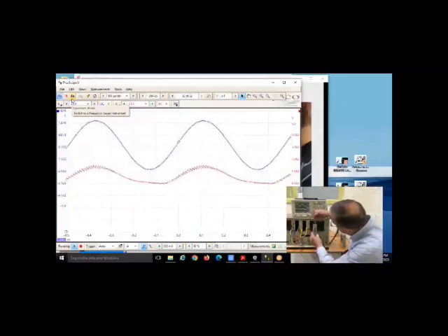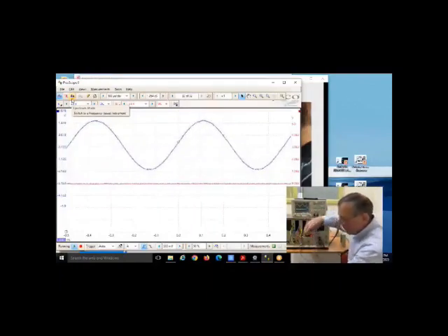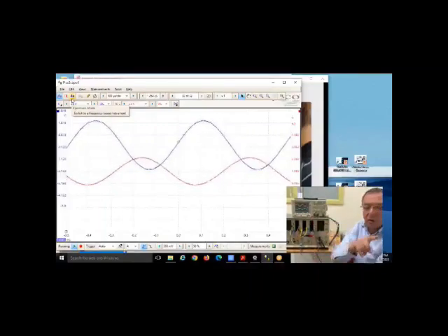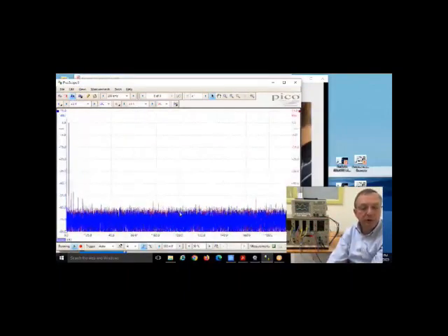Let's use a 5th order filter instead. And I'll just quickly patch this across. And look. So why don't we see 100 kilohertz ripple? Because look, at 100 kilohertz, the roll-off of this filter has completely suppressed the 100 kilohertz component.